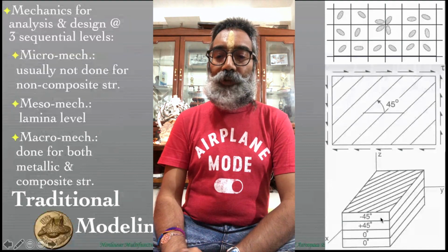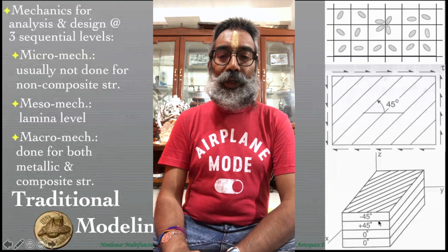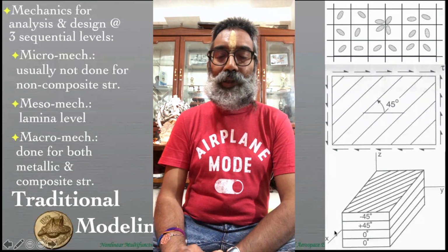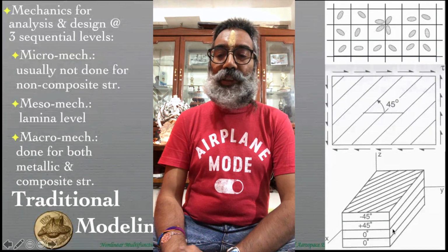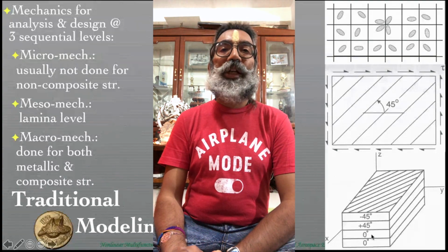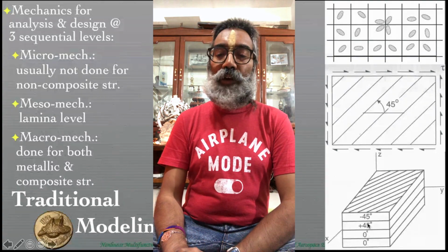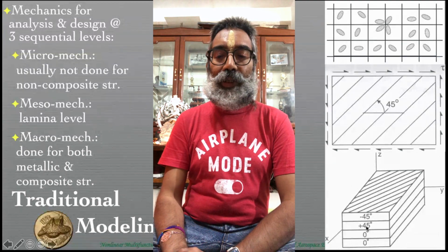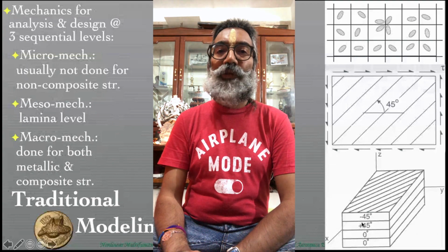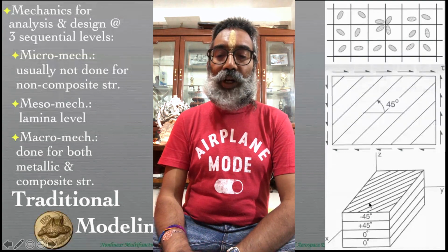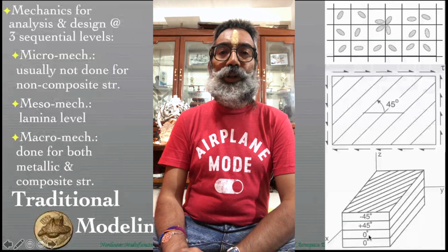So if you think of all of these 4 layers in this laminate as being of equal thickness, and the mid plane is basically over here, above the mid plane, immediately above you have plus 45, whereas immediately below you do not have a plus 45, you have a different angle, and therefore it is not symmetric. If it was plus 45, it would have been symmetric at that level, and if it was minus 45, then it would have been antisymmetric. But that has to be done for all the layers on the top and all the layers on the bottom.